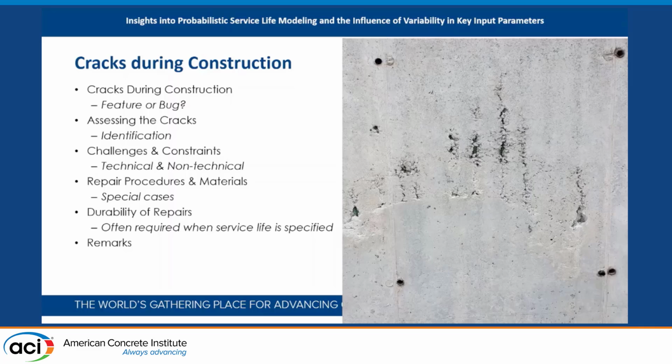Understanding how cracks affect concrete, specifically in service life prediction, is a tricky thing because there are a lot of variables that can affect the performance in different ways. So assessing the type of cracks, or sometimes it's not even a crack, it could be something like bug holes or defects. These types of construction features will affect the way the structures behave and how you can make predictions of their behavior or performance.